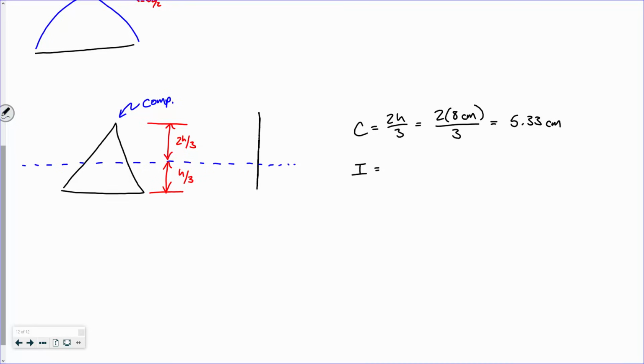Okay, so here's our bending stress profile, and it does sort of that whole thing. We measure that with My over I, where y comes from the neutral axis. So C is from the centroid to the very top of the beam, or the other way around to the very bottom. Since the top is experiencing compression and the problem is asking for the largest compressive stress, I went to the top. Make sense? If it was looking for tension, we'd go to the bottom.